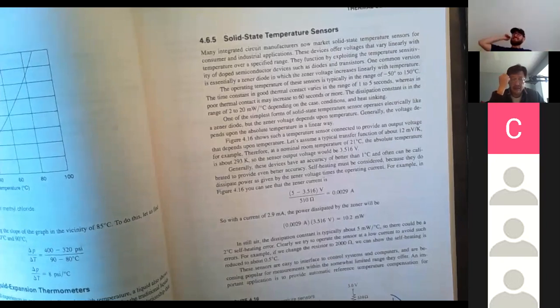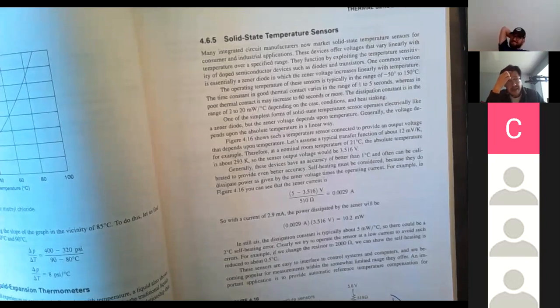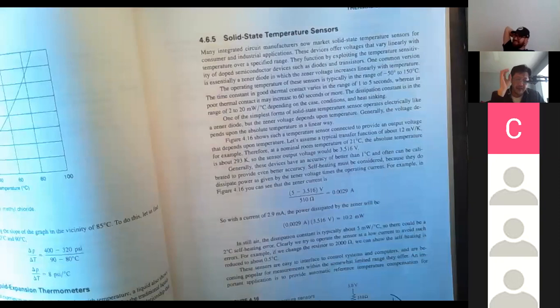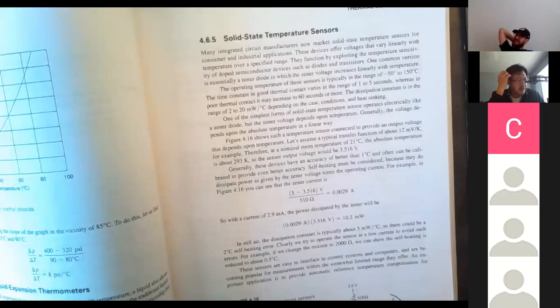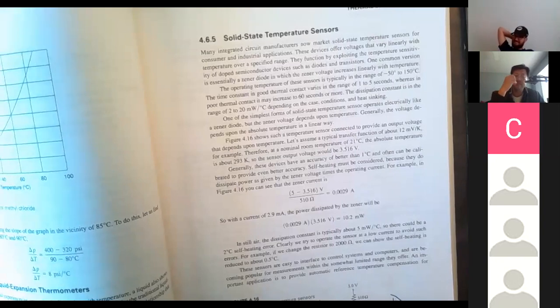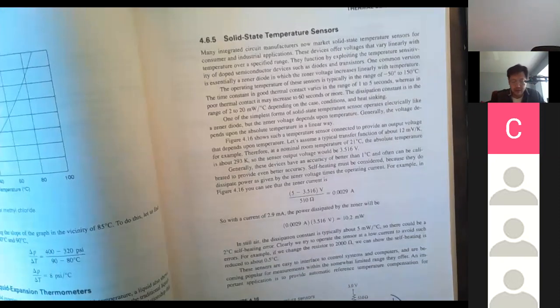I was there. One of our graduates works right there as an engineer. They have dozens of those sensors. They don't put one in every battery, if I remember correctly. They put one maybe every 10 batteries. They have thousands of batteries charging at the same time in their plant. They put those sensors every 10 batteries, and they monitor those temperatures and then use the temperature to control the charging current.